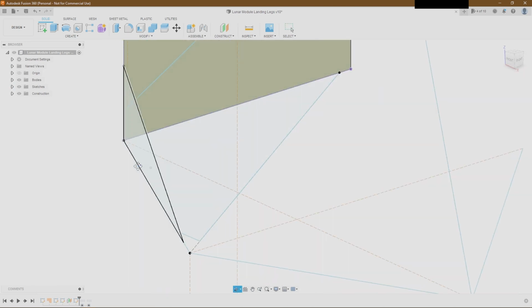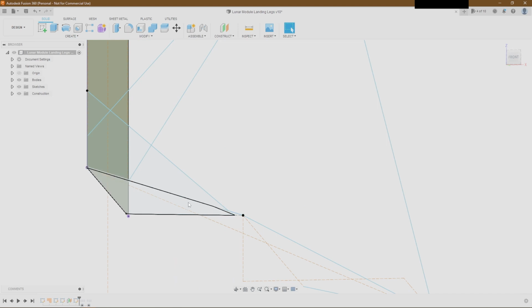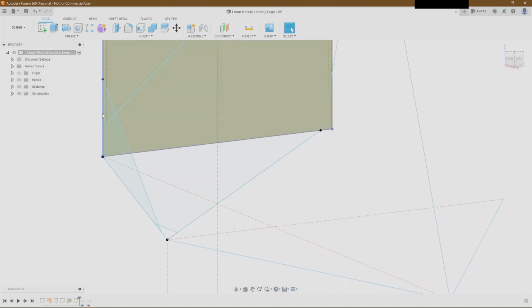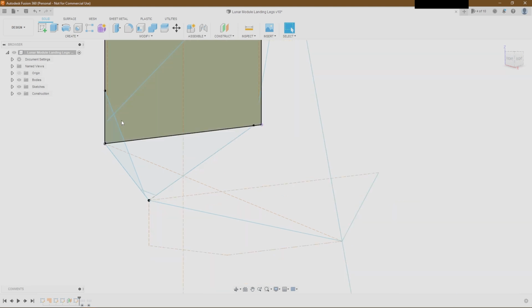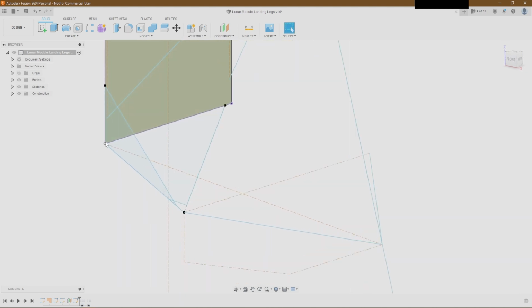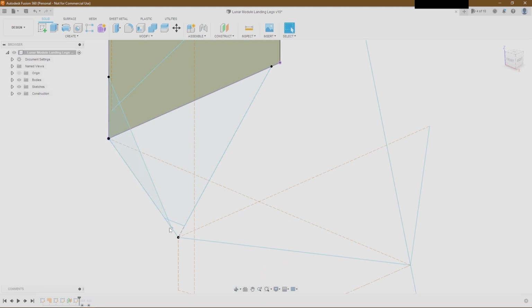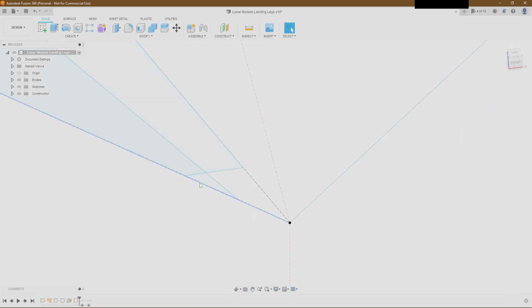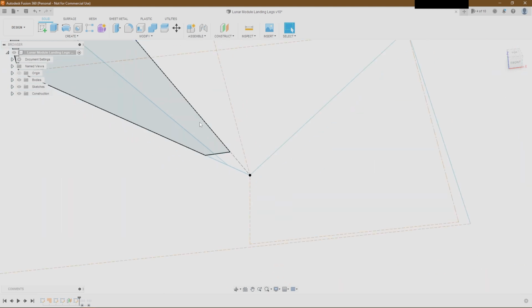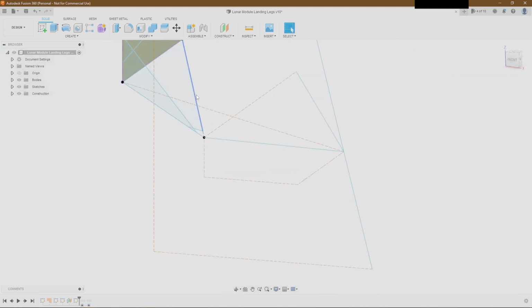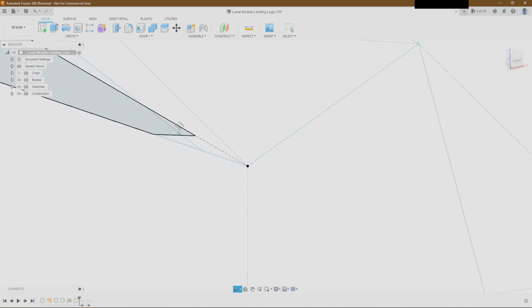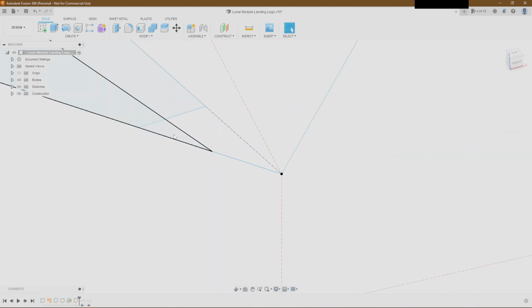So same thing over here. So here's the triangle. Triangle struts. You can see I abstracted away essentially all the extra stuff here. If we were doing a very detailed analysis model, we could include those. But then here we have the fork. So you can see it forks right here and then attaches to this cross brace assembly right there. And again, I have reference lines to make sure it's all constrained. And then the strut interfaces after the fork.